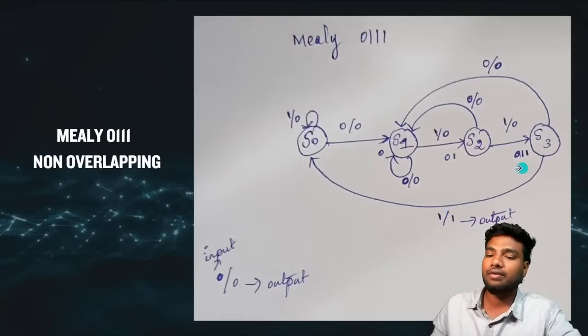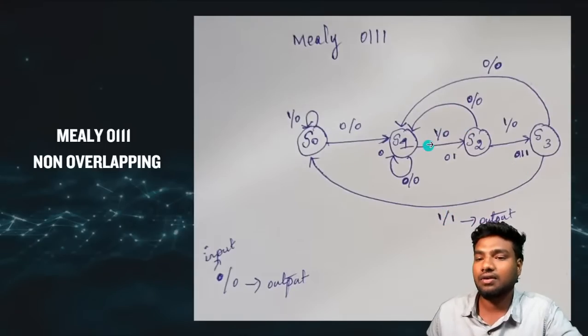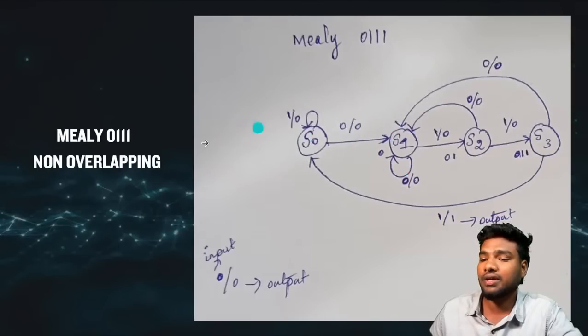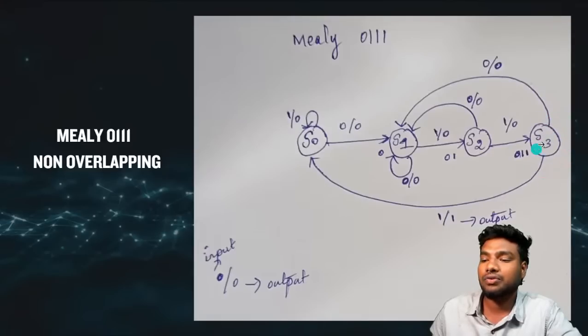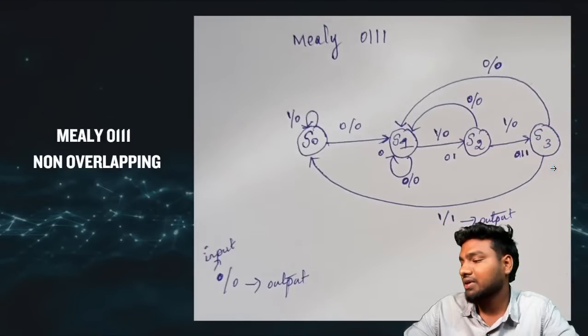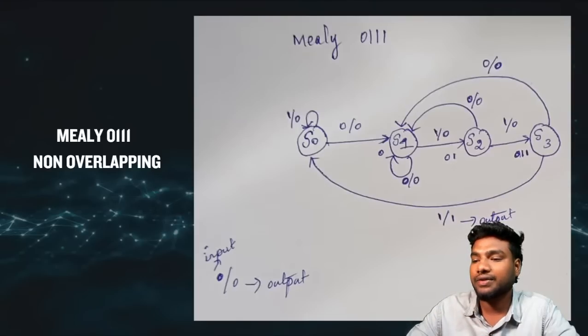So this is a basic Mealy machine FSM, a finite state machine. It has 4 states. The output of the FSM can be known by the transitions, so there is no separate state to know the output. In a Moore machine we have the additional output state, like S4.